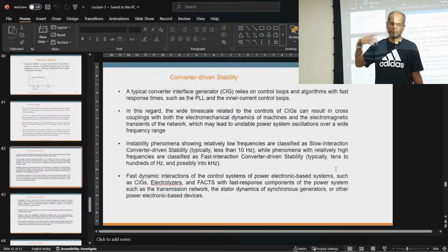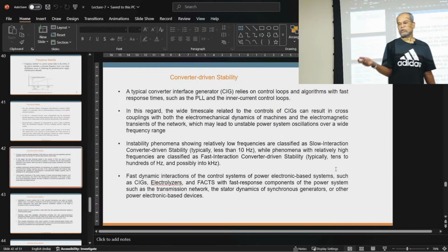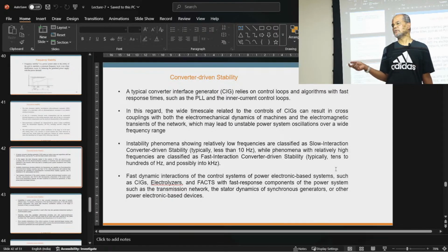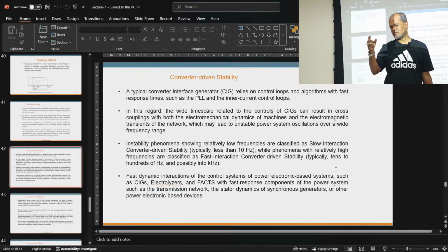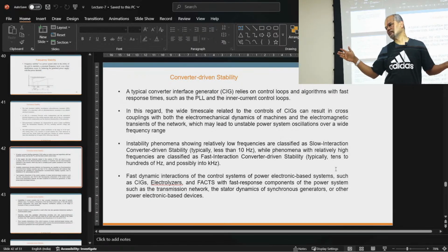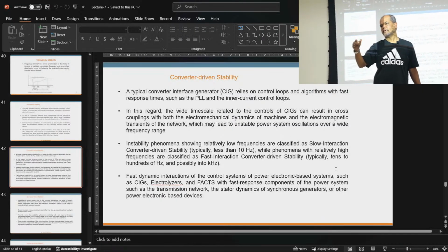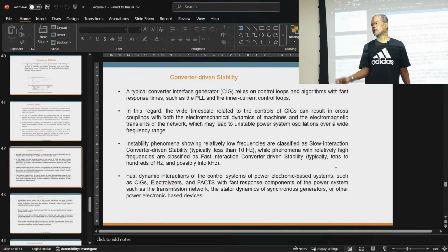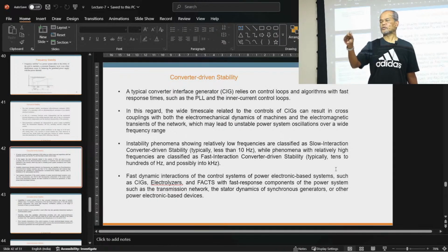And also, for those who are doing voltage stability, it depends on whether it is short term or long term. The phenomenon that I was explaining is short term, but sometimes voltage instability can also happen over the long term, due to OLTC and over excitation in the generator as well, the exciter.